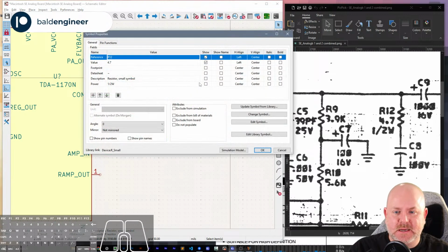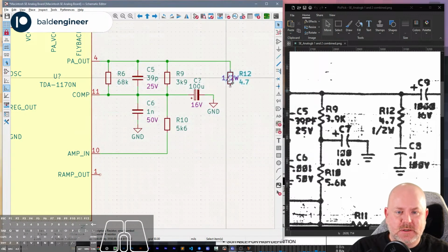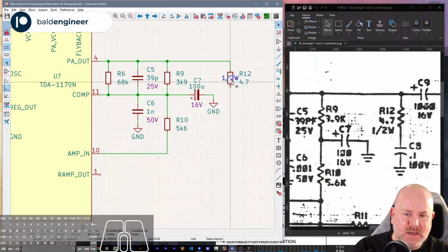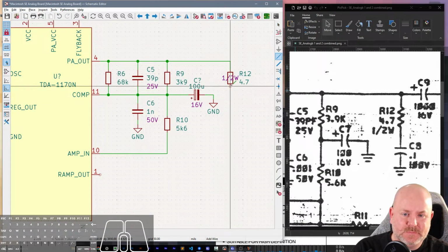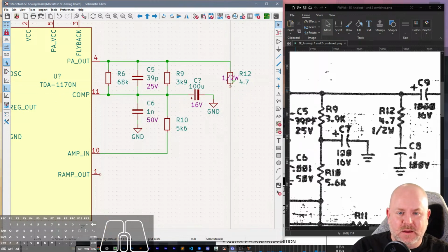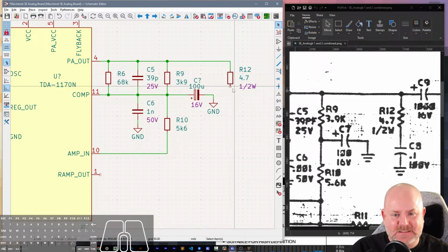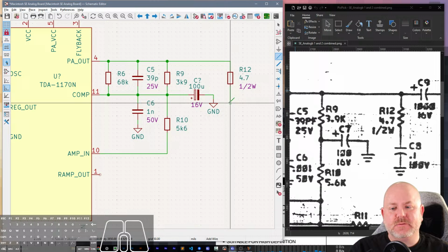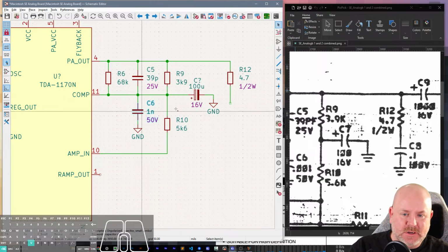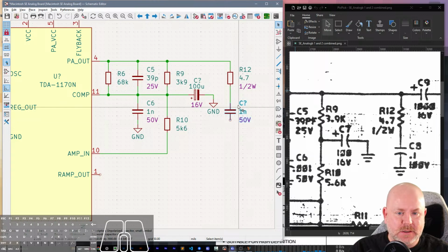Oh, forgot to say show. And then if I hit O, does that line everything up? Let's try it. So I select the symbol. Nope. If I select the symbol, okay. I'm going to press and hold. I want to select the symbol and then press O. Yeah, look at that. That's nice. O basically resets the auto positioning of fields. I don't think that's new. I think that's been around for a while, but it's new to me.